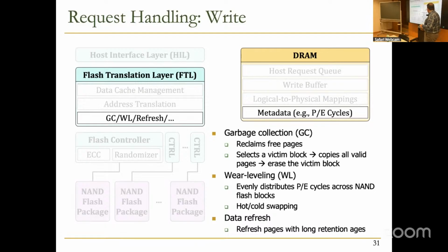And data refresh, which is needed because even though flash memories are considered to be non-volatile, you're going to see later that we actually need to do refresh at least once a week, for example, or once a month. If you, for example, store some data in your flash memory, and you don't touch it for, let's say, 5 years, and after your graduation, you just connect that flash memory, good luck getting your data. You might not actually get your data.